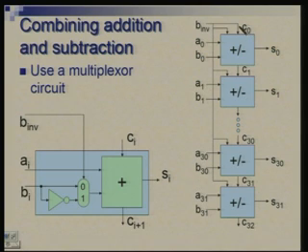The carry input also needs to be controlled, and it so turns out you can use the same signal BINV. So, when this control signal BINV is 0, the initial carry is 0 and the bits of number B go without inversion. When this input is 1, the initial carry becomes 1 and the bits of B, B0, B1 etc. go via inverter. Okay. So, this control signal is going to all these modules.